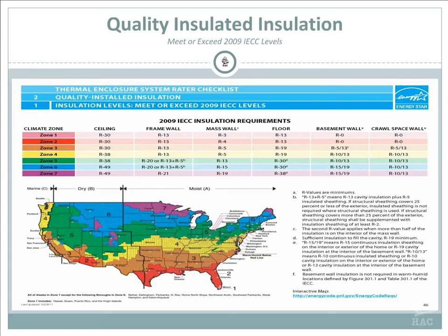Okay, we talk about the framed walls. This R13 is basically just a 2x4 construction. That's about how much insulation you can put into that wall. Again, when you get into Zone 5, Zone 6, it talks about an R20, or you have to have an R13 inside the wall with an R5 minimum continuous insulation on the outside. So again, that's what that means. When you come into an R13 plus an R5, the R13 is on the interior, the R5 is on the exterior. And we'll show you pictures of this in a little bit.